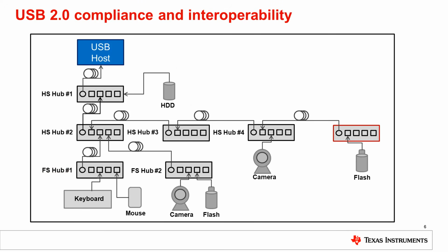So will an end user be able to tell if a product is using eUSB2 or not? No, they won't. In the USB ecosystem, an eUSB2 repeater would count as a USB 2.0 hub tier. In the typical USB 2.0 interoperability test tree used for USB compliance testing shown here, you can see the USB 2.0 specification supports a maximum of 5 hub tiers connected with 5-meter cables.